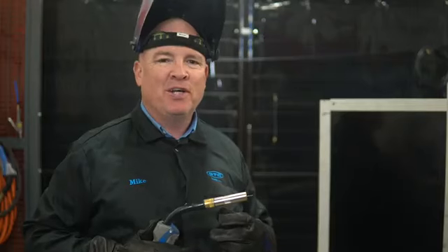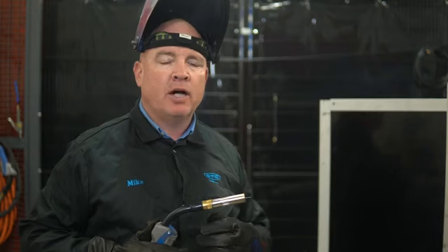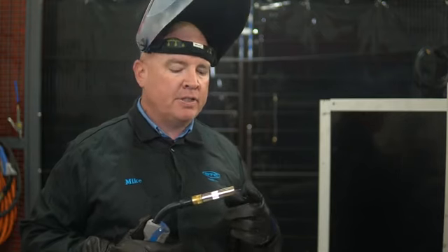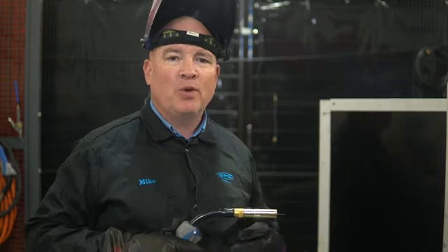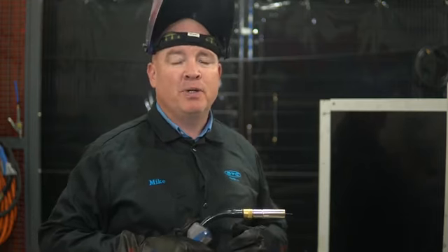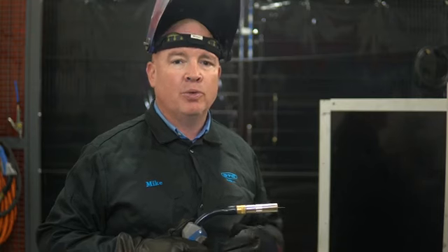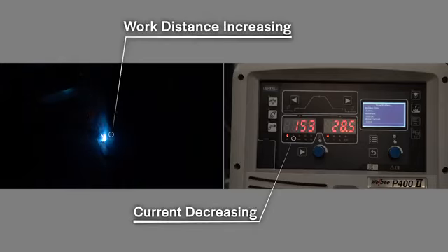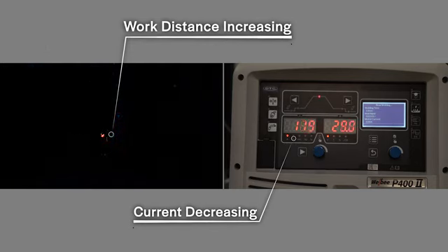One thing unique to the OTC Welbee II power source is a feature called constant penetration that compensates for varying tip to work distance during welding. With Welbee II constant penetration mode turned on, as tip to work distance changes, amperage will remain the same. With constant penetration turned off, welding current dropped from 180 to 117 amps as my tip to work distance increased.